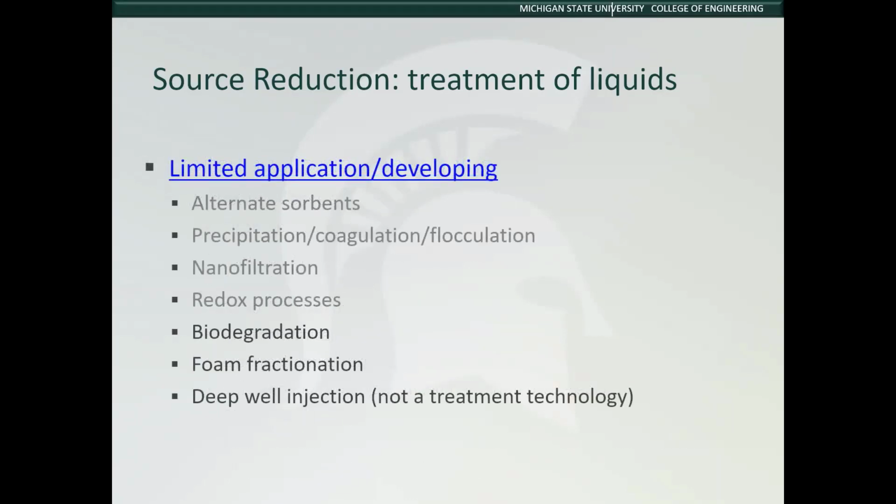Additionally, biodegradation has been studied, attempting to find an organism that is capable of degrading the PFAS chemicals. Foam fractionation has been used along with deep well injection. And just as a reminder, deep well injection is not a treatment technology, but it has been considered as a way of disposing of the liquid concentrates.